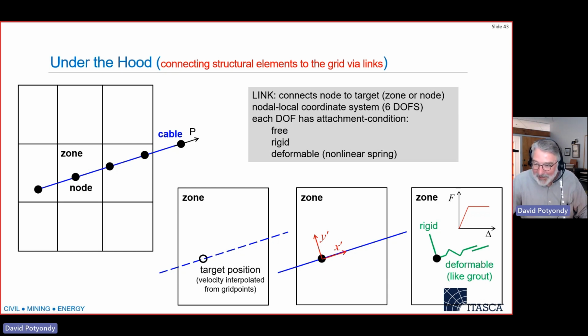like the grout. So that nonlinear spring has a stiffness. So here we're looking at the force in the spring versus the displacement, the pulling displacement in the spring. It has a stiffness. That's why this has a constant slope. That's the slope. And then it has this ability to break, and it has the ability to slide. And so this is the frictional, there's a frictional component here that's meant to show like a frictional rheological component.